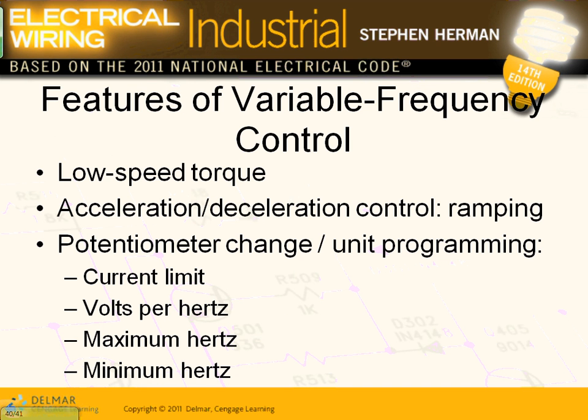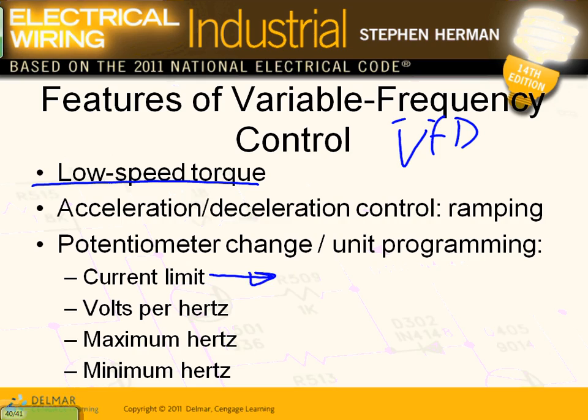The last thing I want to talk about, guys, is when you have a VFD, without getting into the low speed, low torque, you can set your VFD settings. When you set your VFD, guys, you need to put the higher current limit. What's your highest limit? Say, I want to see 100 amp. Okay, what is voltage per hertz ratio? I'm going to use a 1-to-1 ratio.